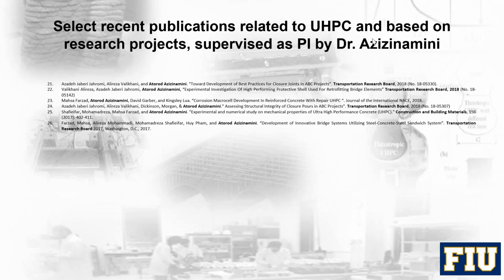I don't know if that answers the question, Melu. Is that what you asked? Well, the two questions were, do the steel fibers corrode in UHPC, and do de-icing salts damage the fibers? No, because it doesn't penetrate through it, because the RCP number that we are looking at is like 15, 20 coulombs. But the fibers that are at the top that are exposed, yes, they do corrode, but that stays at the top. That's it. Nothing more than that.